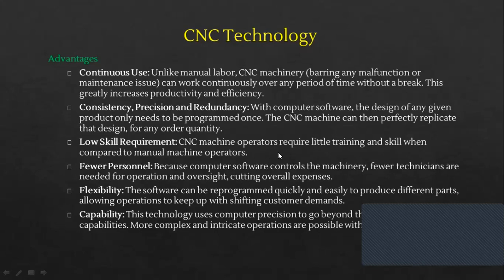With the left hand they operate the feed rate, and with the right hand they operate that wheel, right? We have a wheel, isn't it? That's how we are able to change the feed rate and depth of cut. Rotating that wheel changes the depth of cut and feed rate. So multi-skilled operators are able to do it both at the same time, right? So that skill